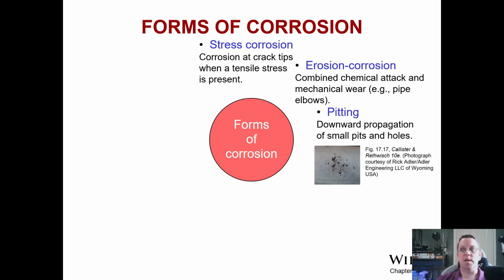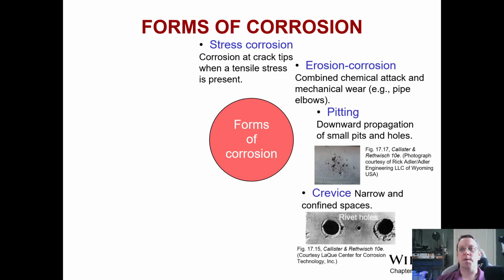So whether it's sitting in ground soil that has some sort of ion exchange happening, pitting also happens in very high sea salty air areas. Near the coastal areas, there's a lot more pitting like this. There are a lot of different examples where anything involving salt water creates conditions for pitting, but there's also crevice type.